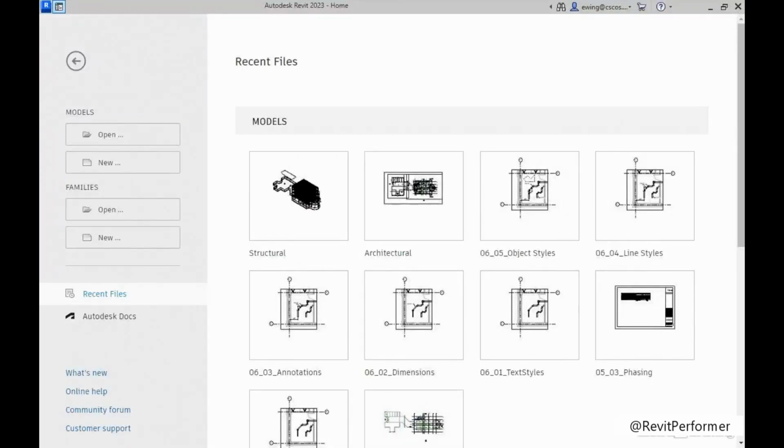Okay, first things first. I'd like to bring in some AutoCAD to our Revit models. There's a couple different reasons why we would do this. One, the more popular one, is perhaps we have an architectural floor plan or something like that in AutoCAD that we want to link into Revit. We can do that. Another thing that'd be nice to do is we have tons of AutoCAD details that are probably set up over the years. We want to start getting those into Revit as well. Get them cleaned up and see how Revit works with them.